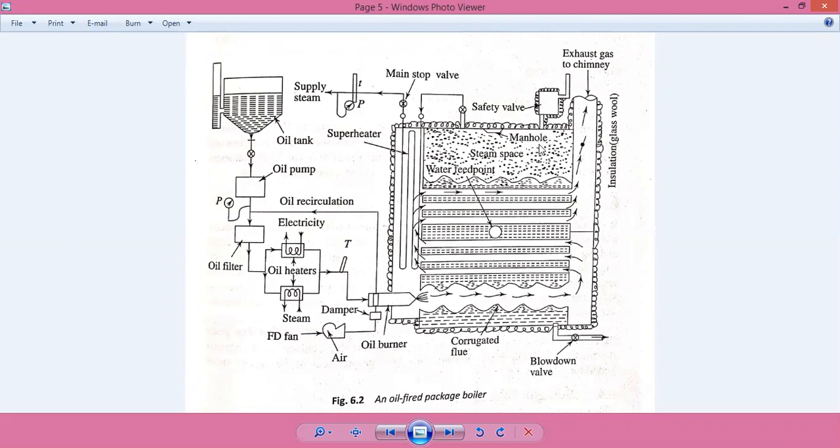The pressure is reduced and the temperature thus increased, and so it is quickly superheated, and part of it flashes into steam itself. But the huge water content is a problem in that it reduces the explosion hazard limit. So we have a proper valve system, safety valve system, which will exhaust the additional pressure of the steam if it goes beyond the limit. Also because of it, a large period of time is required to start from cold to hot position and from hot to cold position itself.